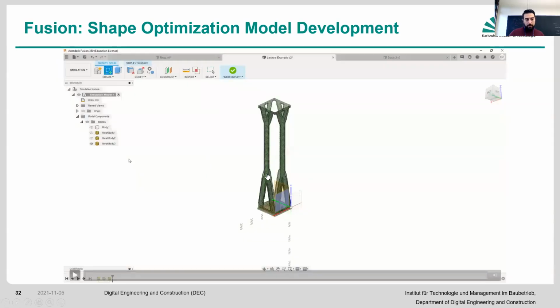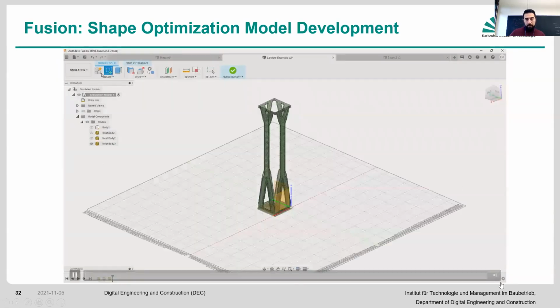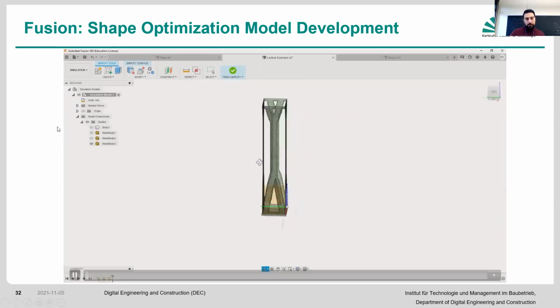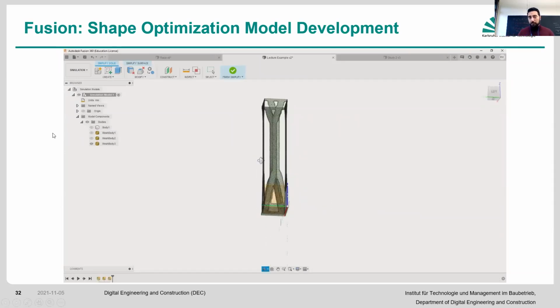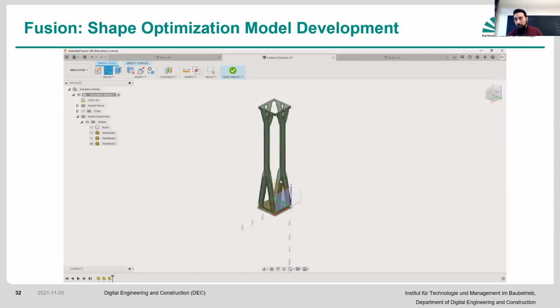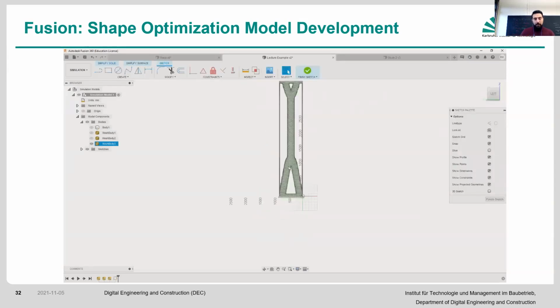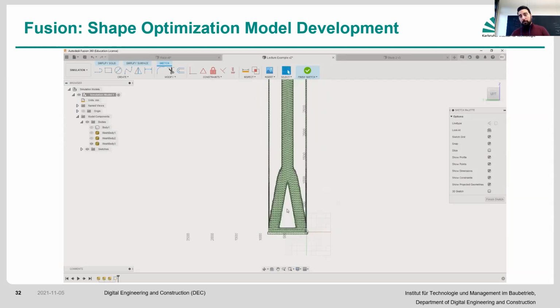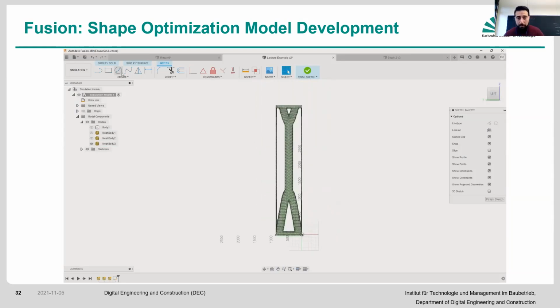And then what we can perform here is, again, we go to that create, and then we find one of these surfaces. Really, this is the beauty of it when it's symmetrical. So we find one of these surfaces and we go and model only one side of it. And once we model one side of it, we mirror it and then take it from there.